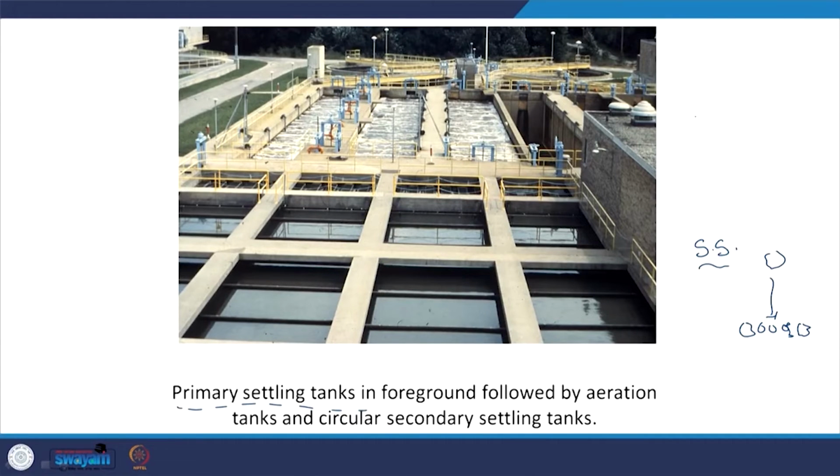But did they design it as a CSTR? Not really. So, how did they design it? They designed it as if the flow was going in this direction and again this direction, like a semi plug flow, or they were trying to achieve plug flow reactor conditions, right. So, that is what you see, it is neither a CSTR nor completely a plug flow reactor, but they were trying to achieve plug flow reactor like conditions.